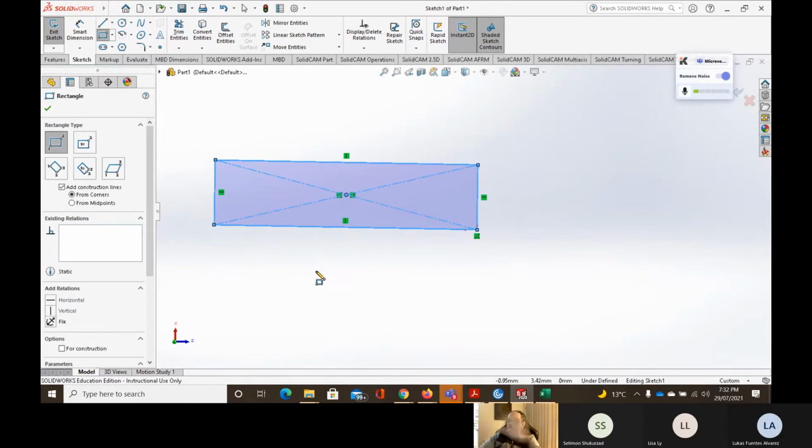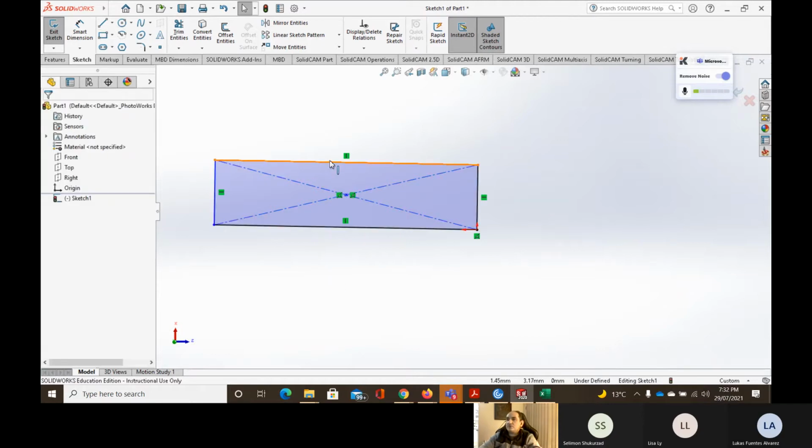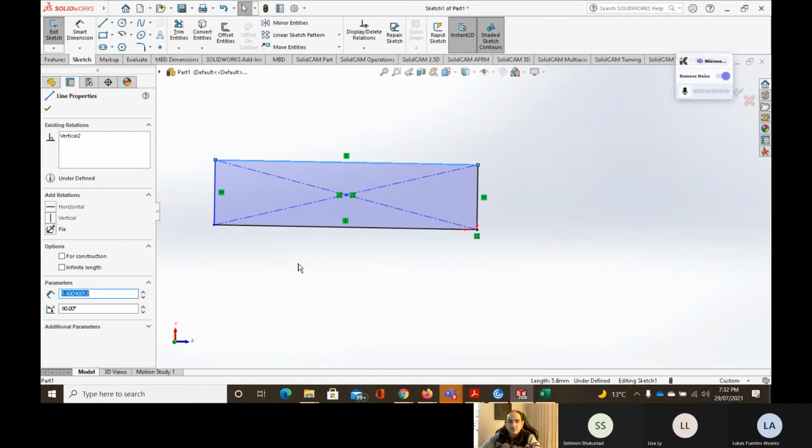So this is the top of the half cross section of the cylindrical shape. I'm going to show you once again if this is going to be cylindrical shape. I'm going to choose, for example, that the length is going to be, let's say, 100. And the diameter is going to be 40, so I'm going to choose 20 for the radius.